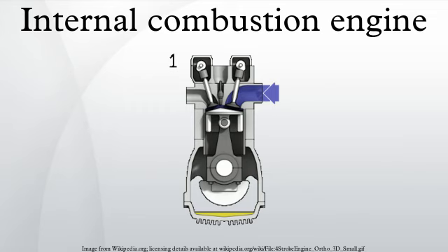Diesel cycle. Most truck and automotive diesel engines use a cycle reminiscent of a four-stroke cycle, but with a compression heating ignition system, rather than needing a separate ignition system. This variation is called the diesel cycle. In the diesel cycle, diesel fuel is injected directly into the cylinder so that combustion occurs at constant pressure, as the piston moves.